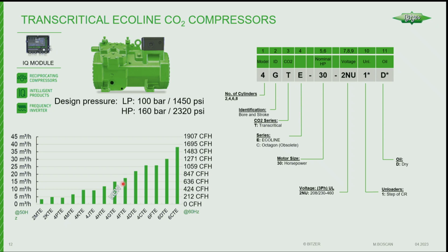That relief valve, by the way, if it relieves, you'll know it, number one. But it blows sideways, so it doesn't blow out the end. You can see it's pointing to the right, but the gas won't shoot out the end. It shoots out perpendicular to the compressor. So hopefully, the idea being you're most likely in front of the compressor if you're close by, and this dissipates it to the sides.